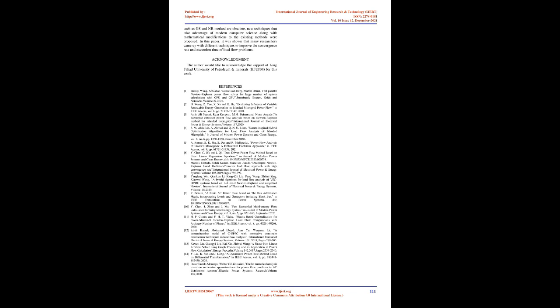Dynamized PF based on differential transformation [14]. As power flow equations are nonlinear, the solution is obtained using algebraic iterations. In order to avoid these iterations, the author of this paper [14] argued that power flow equations, which are nonlinear in the time domain, can be converted into linear equations in the domain of power series using differential transformation, DT.